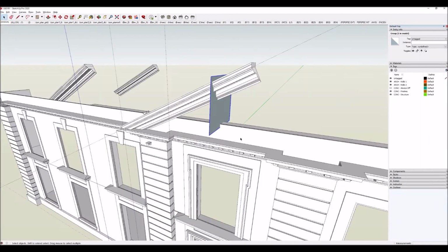for my little bracket. Okay, so I've taken that cyma, that top piece there, and I've stretched it all the way out up to the top here. So I've got lots of extra here. And then I made myself a little surface, simple rectangle, which is aligned with the center line of the building now. And I've pulled it up to where it intersects both the cyma and the rest of the cornice.